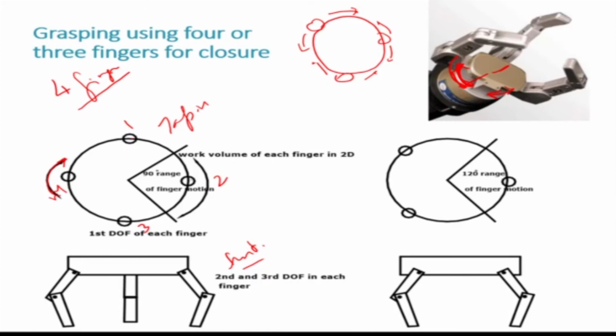The question being asked here is, in order to have form closure of this object, where would you place your fingers? What is the motion plan? With 4 fingers, point contact without friction, we can obtain form closure. On the right hand side, we have point contact with friction. In this case, 3 fingers are enough. So 3 fingers can be used to obtain force closure.